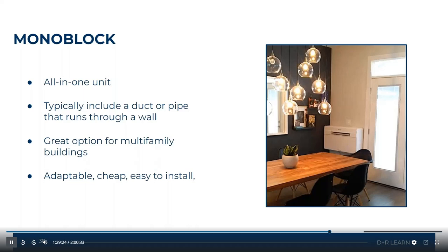So hopefully that answers that question with these mini split systems. It's based upon how your site is designed, and you're going to have to figure out how that airflow is introduced into the space, whether it's by louver installed in a door, a window, even an exhaust fan installed in that space as well. There are many different options that you can choose from.